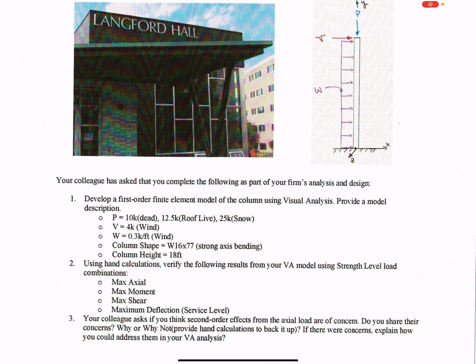There's a big change when we went from ASCE 7-05 to ASCE 7-10. We made this jump and they decided, well, we're already calculating earthquake loads at strength level, so we're going to calculate wind loads at strength level to give a better comparison between the two. There's a lot of probability and statistics buried in all of that, but that's what they decided to do. So when we calculate deflections for those two things, we do 0.6 for wind. What do we do for earthquakes? 0.7. And the intent there is to reduce it to what we're actually going to see.